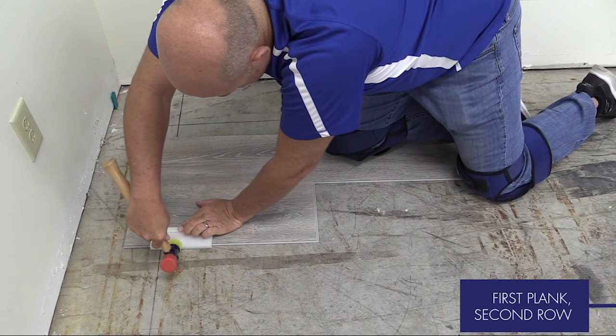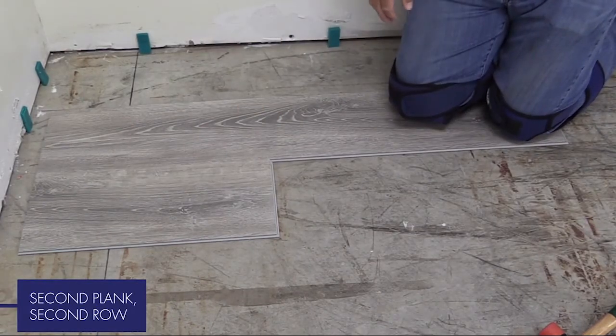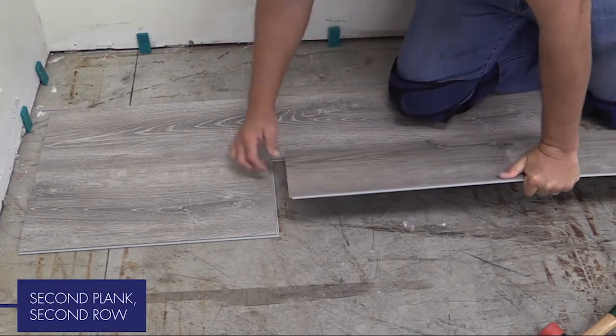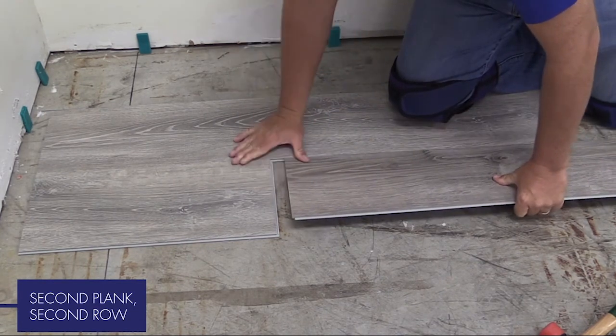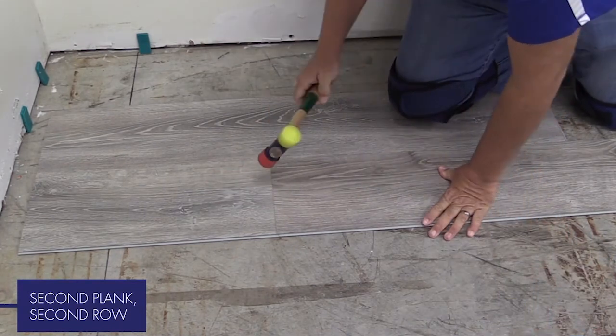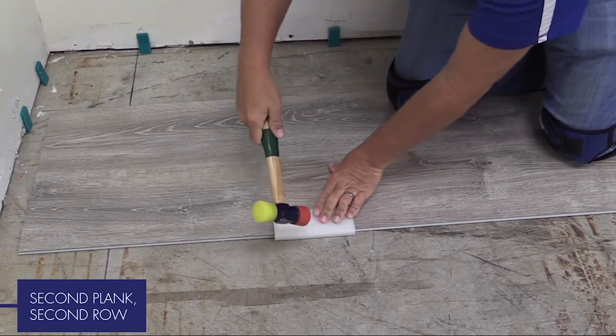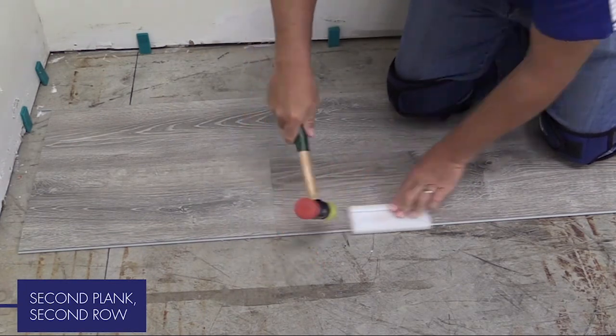Installation alternates back and forth between rows 1 and 2 for the first 2 rows only. Insert the long side of the second plank in the second row. Then slide it until the short tongue touches the short groove on the first plank of the second row. Press into place and tap the short joint with a lightweight dead blow hammer. Then square the joint by tapping the long edge of the plank using the tapping block.